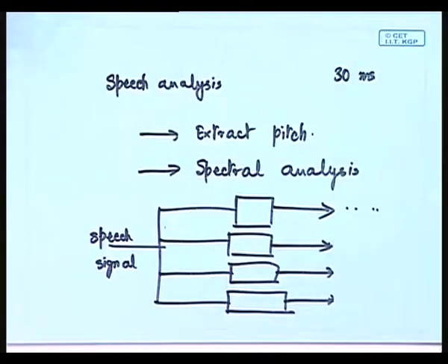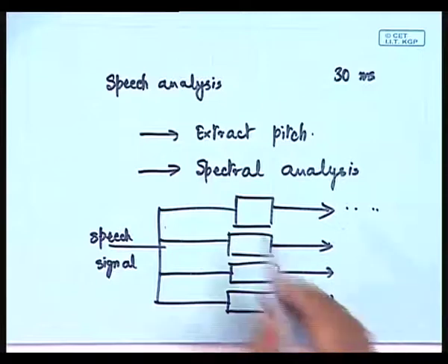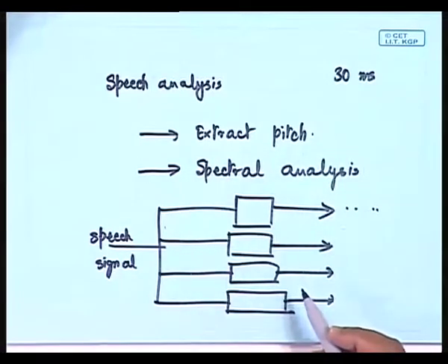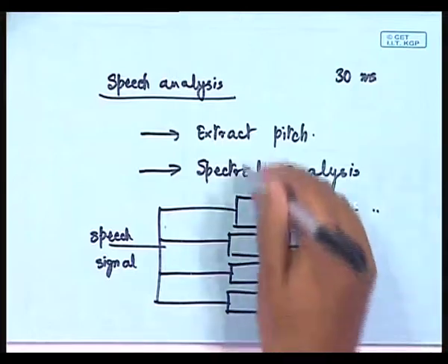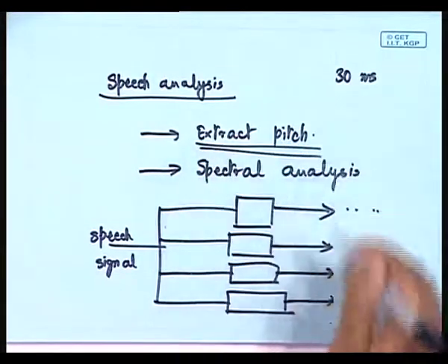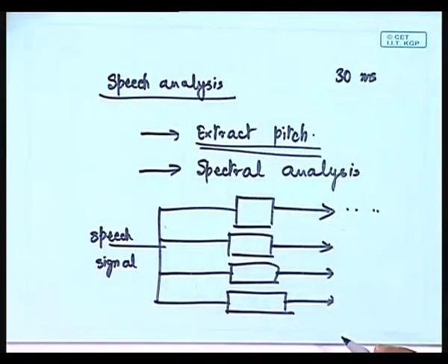So, if we have the individual bands' energy, and if we also extract the pitch information reliably, then we can have an encoding after our speech analysis results. How? First of all, we will be encoding the pitch information, that is, the pitch frequency that we have observed, and we will also encode the energy of the different filter banks.